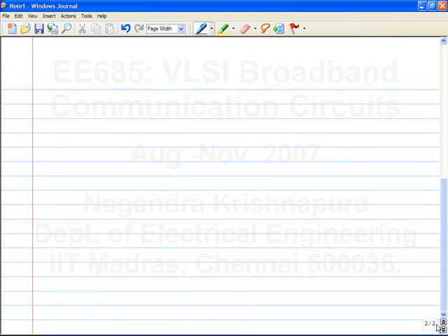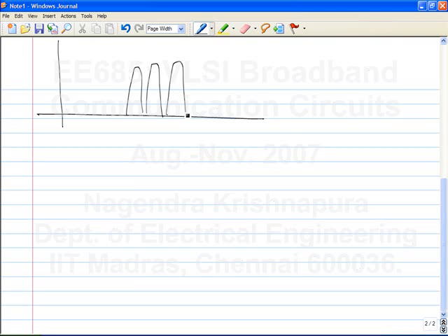When you have a common medium across which you have to transmit multiple channels, you will opt for narrowband, because using different frequencies is one way of distinguishing between different channels. If you have a common medium like air, and all signals have to be transmitted across the same medium, then the most obvious way to distinguish between them is to use different frequencies for different signals.